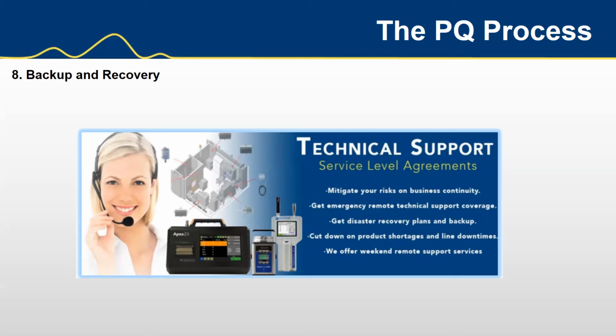Number 8, let's look at backup recovery. This critical process needs to be exercised during the PQ. System backup and recovery has a major importance attached to it. As particle monitoring data is GMP data, there should be a couple of layers for data backup. For example, data buffers built into the particle counters. Will they still sample data if the network was to go down? Yes, with some of the models out there you can have a couple of days' worth. Then you can buffer those results back into your system and have retrospective reports made up to see if you were still in control, and that will help you make a decision on your batches.